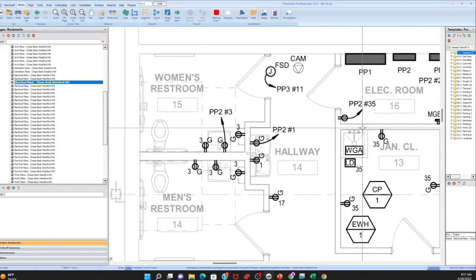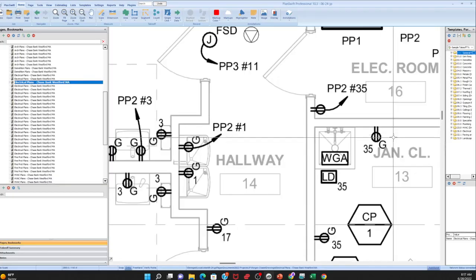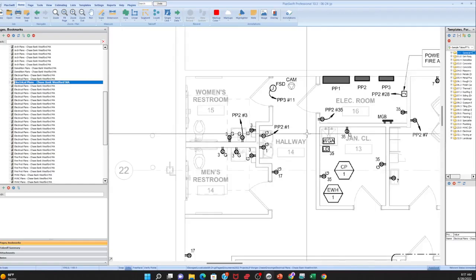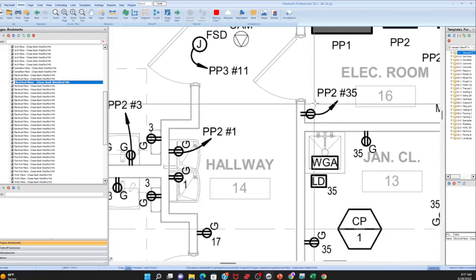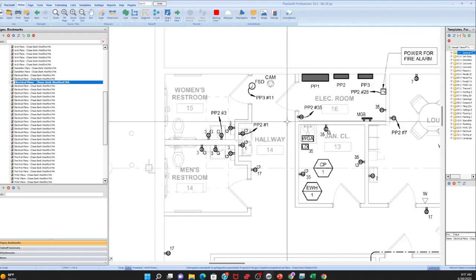So the thing about the electrical, the symbol is supposed to tell you. You're supposed to be able to look at this, look at the symbols list, and get an explanation of what it is. When I do the takeoffs, I always do the counts first. I'm going to go through and do my counts, but then I also have to do the wire runs. That's why I start with the electrical set, because it is more, I want to say a pain, but it's more complicated.